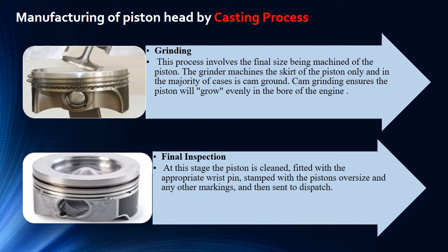And lastly, the final inspection. At this stage, the piston is cleaned, fitted with the appropriate wrist pin, stamped with the piston's oversize and other markings, and then sent to dispatch.